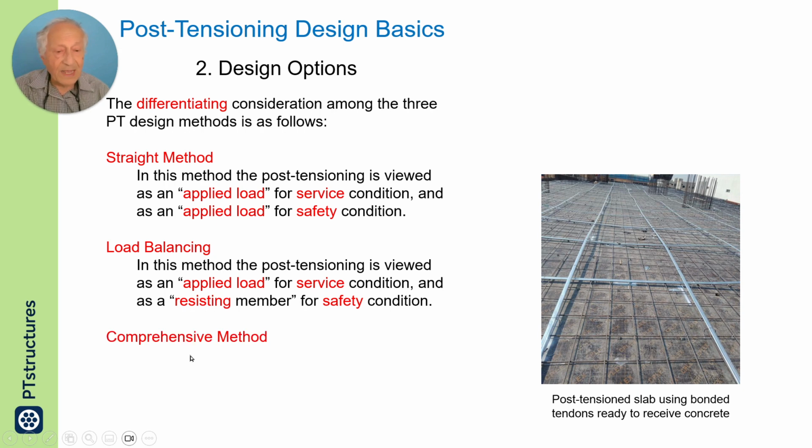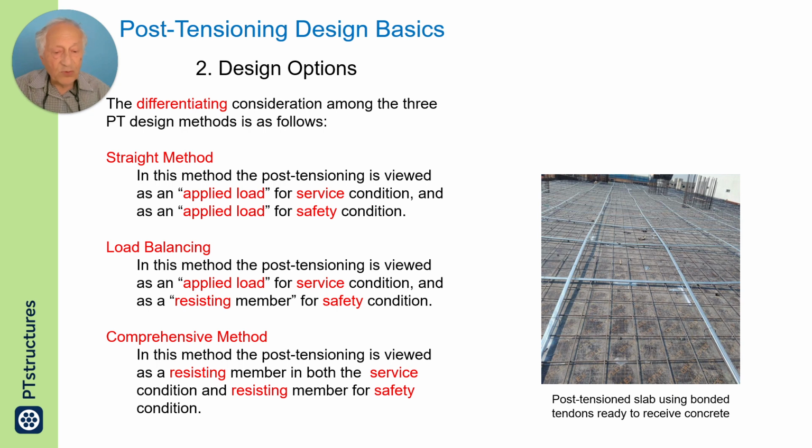In the comprehensive method, the post-tensioning is viewed as a resisting member in service condition and as a resisting member in safety condition. So it is considered to be on the resistance side. You know, you have the demand side and the resistance side. In the comprehensive method, it was on the resistance side in both cases.